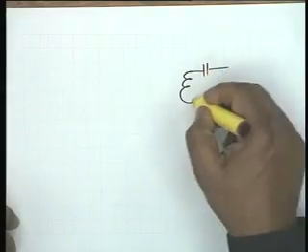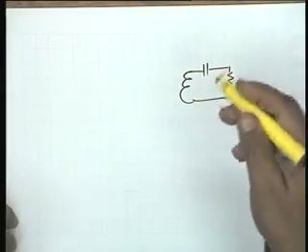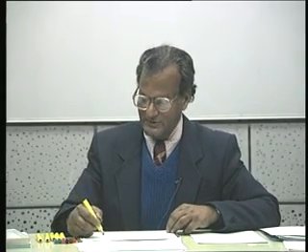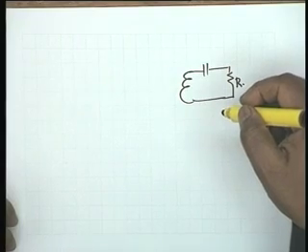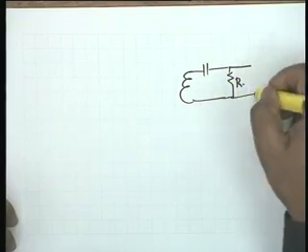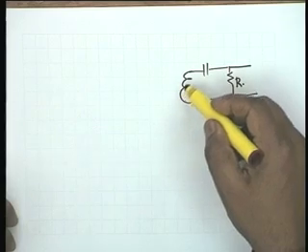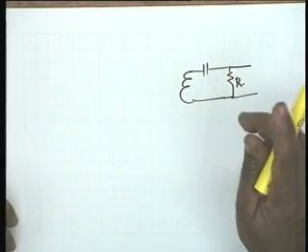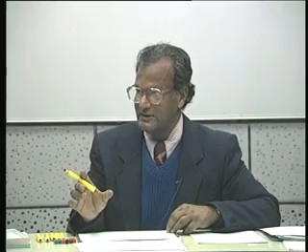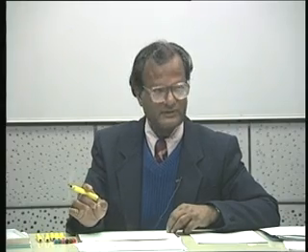It might so happen that the secondary has to transfer power to, let's say, the input of an amplifier stage. The input of an amplifier stage, the impedance is basically resistance. So this resistance is inevitable. Then you will have to change your coil and capacitor to be able to adjust to the particular band of frequencies and the sharpness of resonance that you really desire.